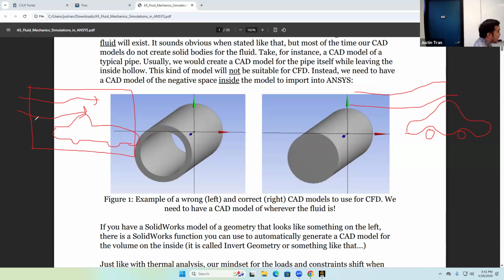Okay. So doing exterior flow CFD is a little bit more challenging because you have to create a box that's big enough to hold your entire flow. And then you actually have to cut out a portion of that box, which is where your solid geometry is going to be. I have gotten a couple questions on that. I'm a little bit less experienced with that, but that's typically how you would do it for an exterior, typically airflow type of simulation.